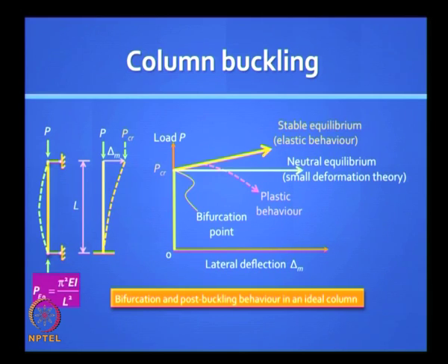You are familiar with this, right? Look at that equation. EI is in the numerator, which means if you had a member with a large flexural rigidity, the buckling load will be much higher, and in the denominator, L is coming into the picture. So if the member is long, then its buckling load is going to be much less. Okay, so these are intuitively obvious, and you can prove for a cantilever it is 1/4 this value. For a cantilever, it is obviously less stiff than a simply supported case, so it turns out the buckling load is 1/4.